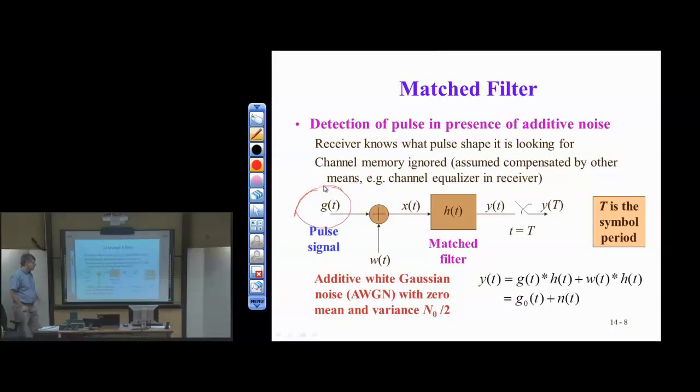It is being distorted, or degraded, really, is the better phrase here, by additive noise. The additive noise follows a Gaussian distribution. It's spectrally flat, so the power spectrum is a constant, and that constant value for the power spectrum is equal to the variance. The historical name, again, is white Gaussian noise. I prefer spectrally flat. I'll use both. And the mean is 0, so we assume that the average value is 0.